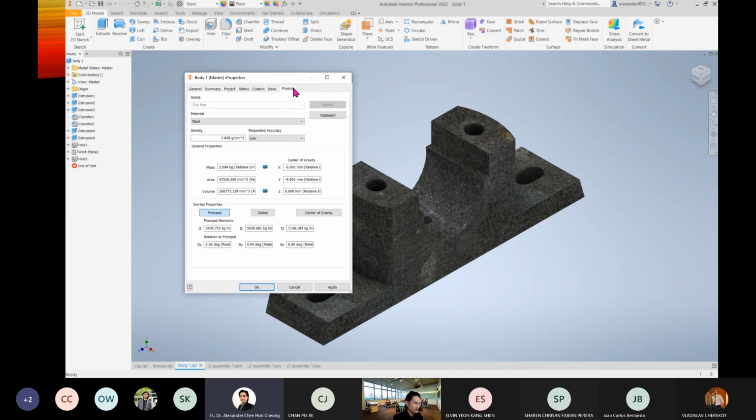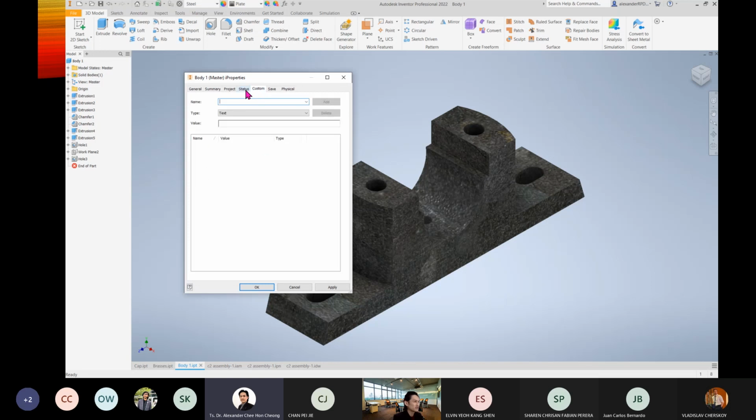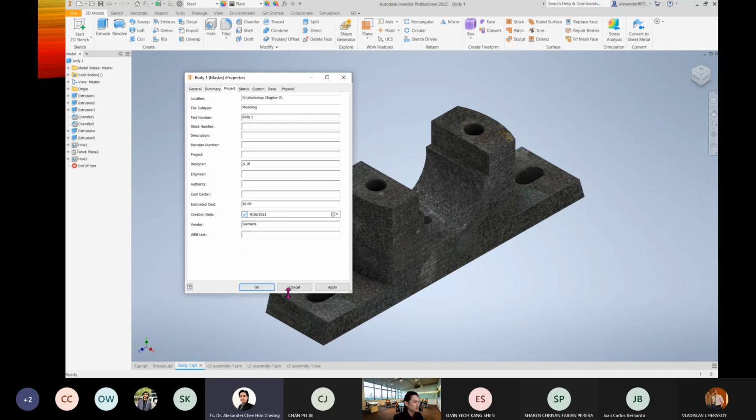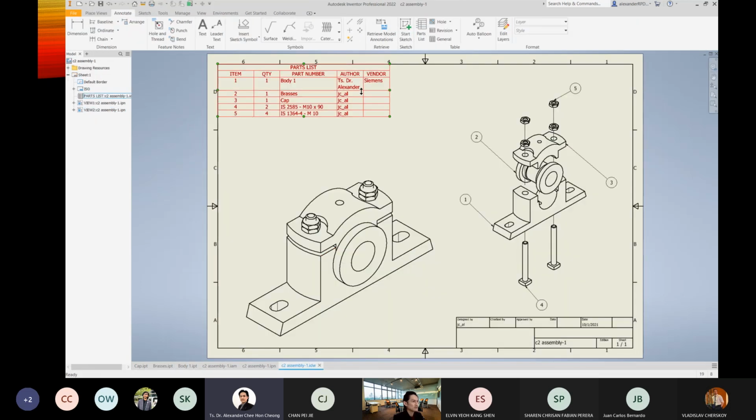But now this one is under simulation, so we're talking about modeling here. So it will be this tab that will be useful. Now I already filled in the author and also the render. So now apply, and I go back to the drawing. So now you see that. I adjust the sizing a little bit. Okay, snap it again. Now you see, but I only edited the iProperties of my body one. So the other...